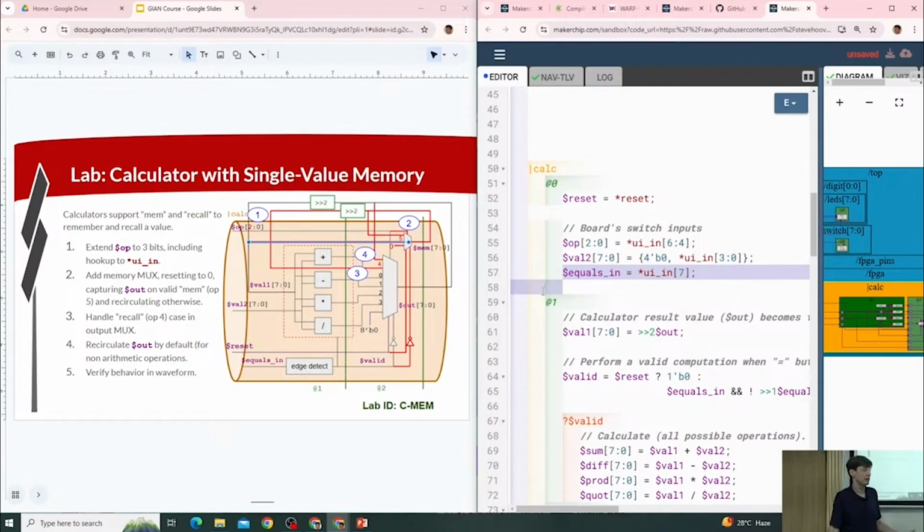Same deal. When you power on, the power has to stabilize. After the power has stabilized, you hold reset for some minimal number of cycles, then you deassert reset. So again, you want to create that synchronous reset and use that synchronous reset everywhere.